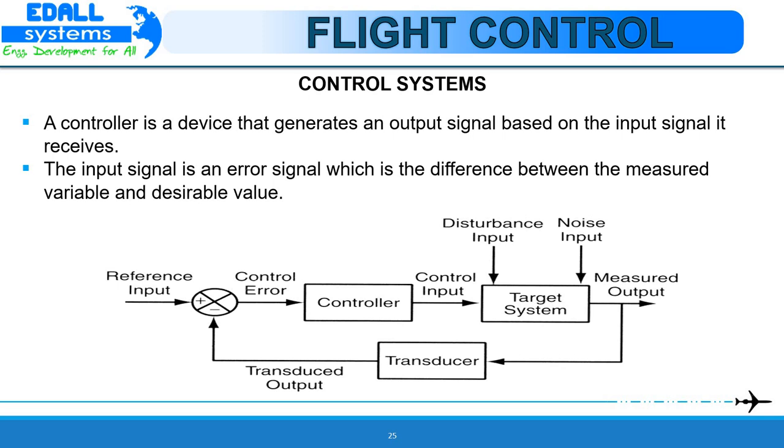When the feedback signal and input are out of phase, meaning having a phase difference of 180 degrees between them, then the feedback is called negative. This error signal is then modified by the controller and decides the proportional manipulated signal for the process to be controlled. This manipulation is such that the error will approach zero. This signal then actuates the actual system and produces an output. As the output is the controlled one, it is called a controlled output or a measured output.